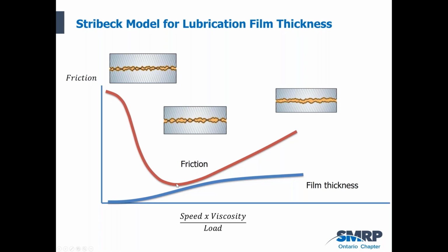And that reduction in friction is due to the fact that the viscosity is creating separation between the moving surfaces, and we're slowly creating more of a gap between the surface that is rotating relative to the surface that is stationary or moving at a slower speed. So that's how the friction changes from pure mechanical down to the low point in friction.